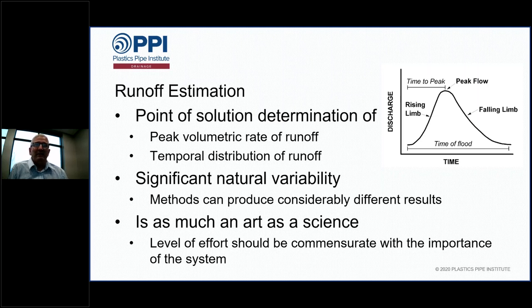So what I'm getting at there is, if you have a culvert that's in the middle of nowhere, and if it floods up behind it, no one gets damaged, nothing gets hurt, do you really need to go through the effort of going through gauge data and things like that? You probably don't. A simple rational equation is usually good enough. So understand the importance of the system when you're determining what is the right runoff method.